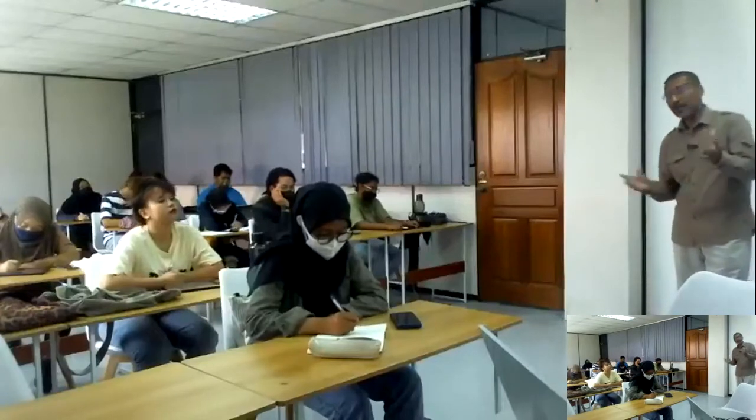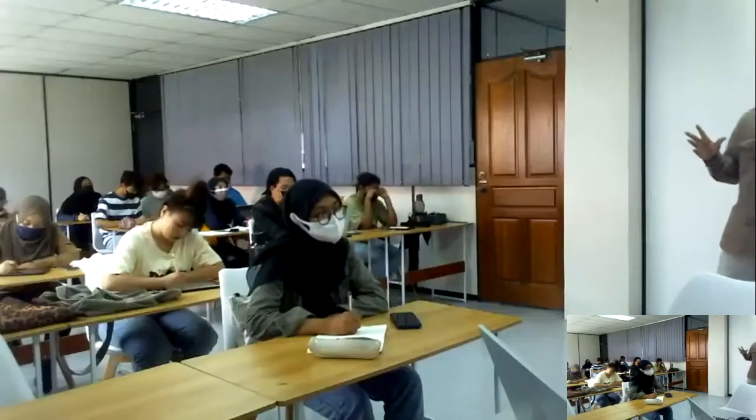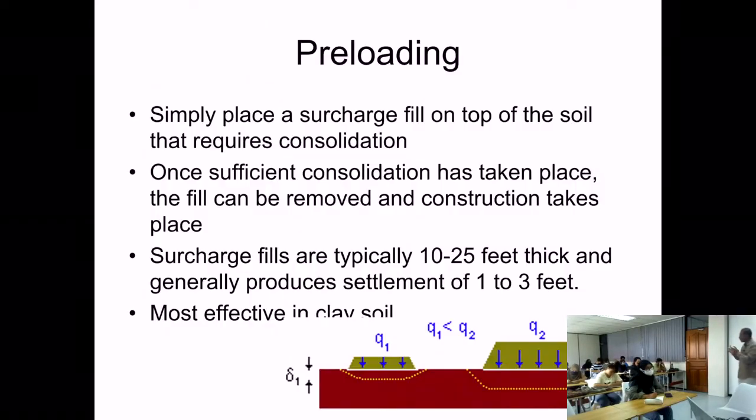Simply place a surcharge or additional loading, fill on top of the soil that requires consolidation. Meaning when the soil consolidates, it becomes stronger. So that's the concept. So how do we get them consolidated? We press them using loading.